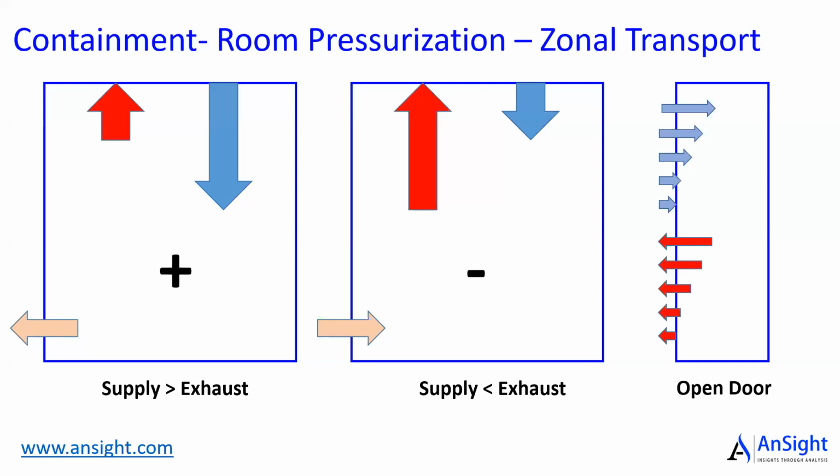One thing to remember is that these pressurization techniques work only when the door is closed, when you have a confined space. As soon as you open the door, there is a bidirectional flow of the air. So outside air comes in and some part of the inside air goes out. So that pressurization fails with the open door. There is a lot of talk about pressurizing the spaces. And if you have frequent closing and opening of the doors, like in a restaurant, office spaces, waiting lobbies, pressurization techniques are not going to work simply because the door doesn't remain closed for most of the time. So this is about pressurization.